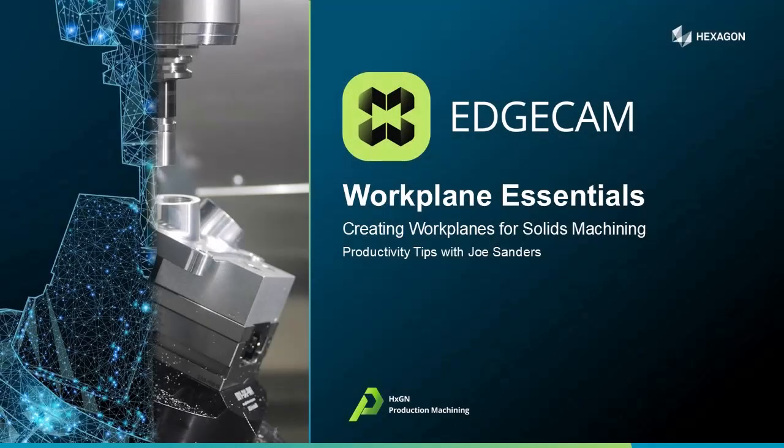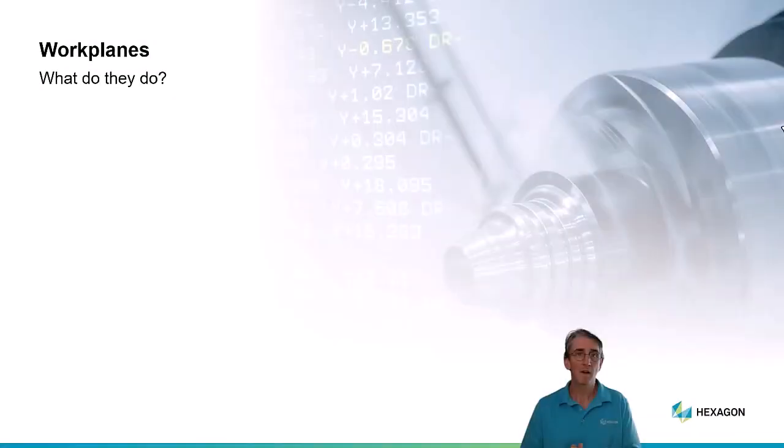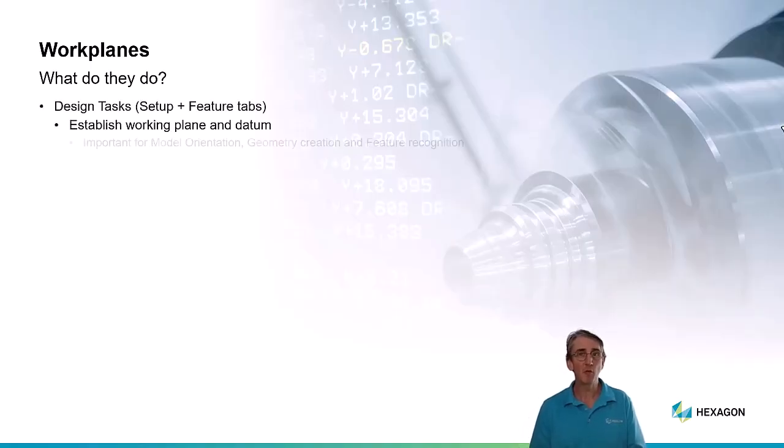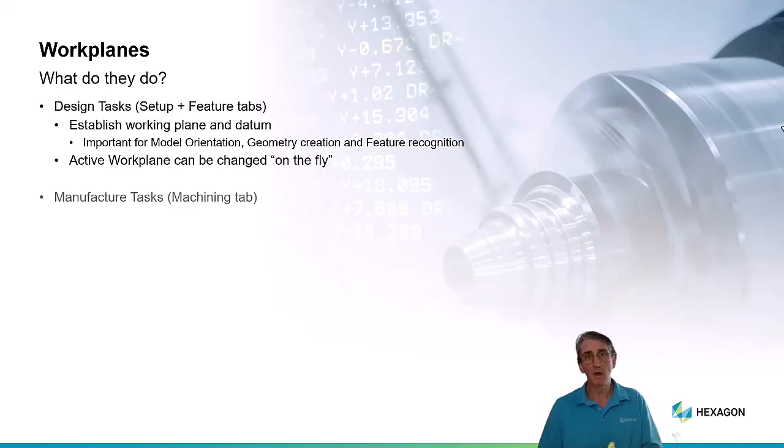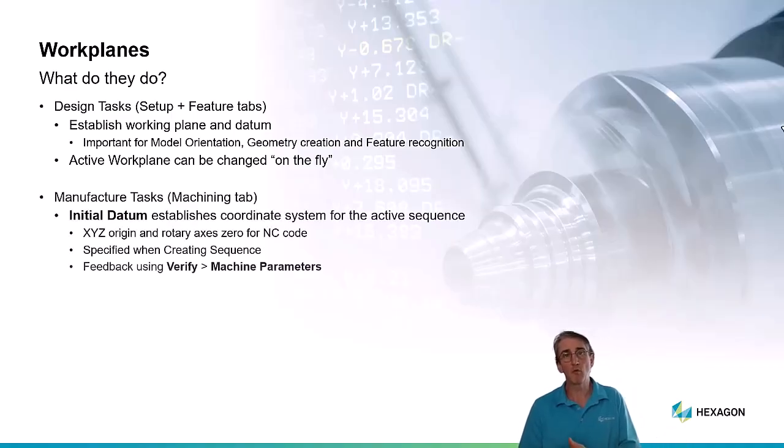In this tech tip, I'll be demonstrating key information on creating workplanes in EDGECAM using solid models. Workplanes have so many uses in CAD and CAM software. Specific to EDGECAM, we use workplanes when we're orienting the part and getting it aligned the way we want, as well as when we are creating geometry and feature recognition. We also use workplanes when we're building toolpath.